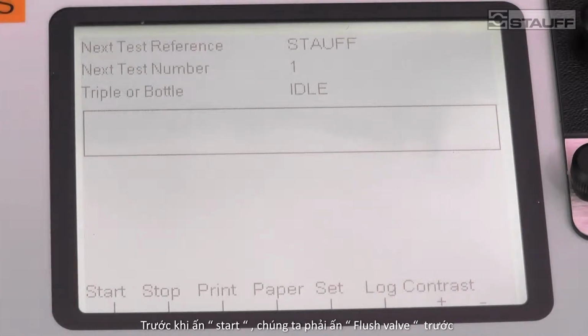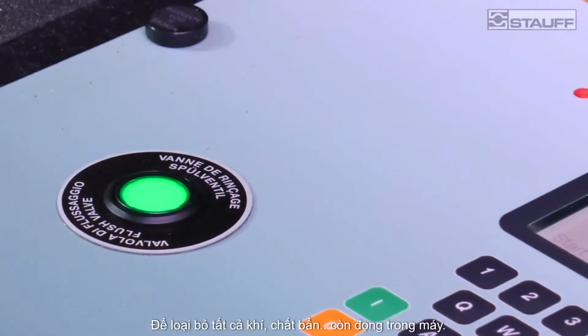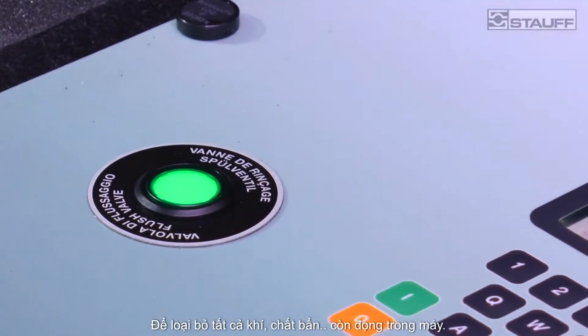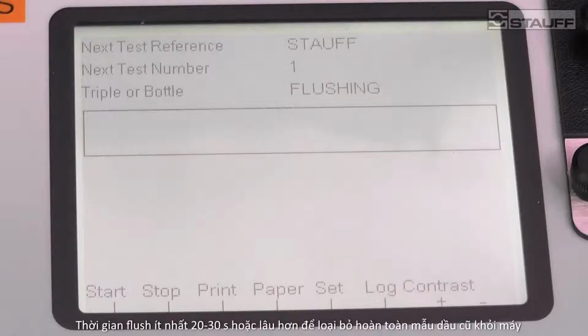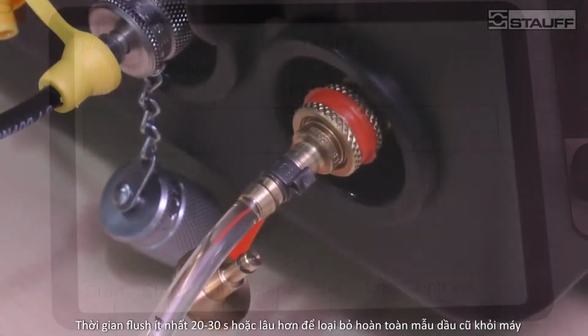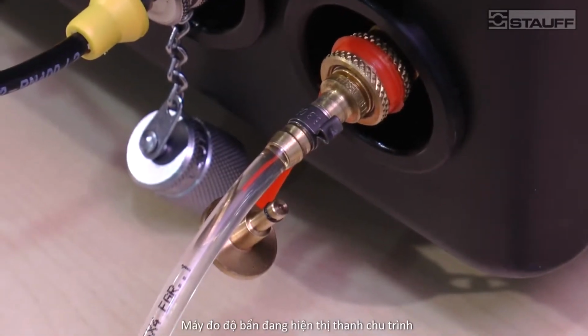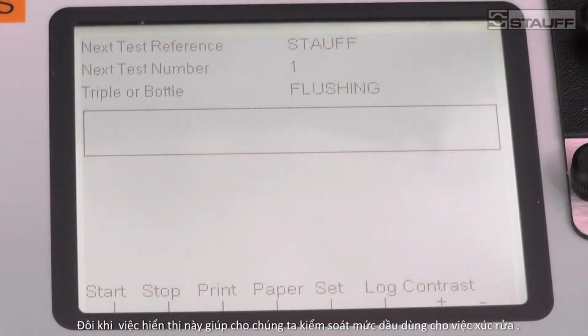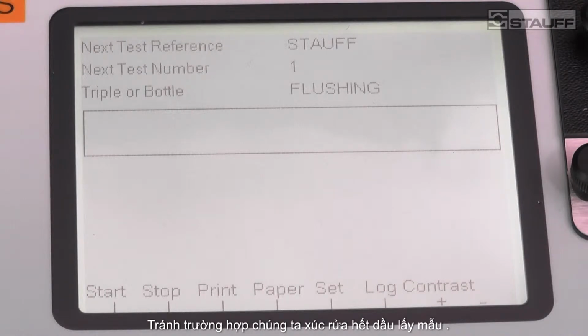Before you press start, ensure that you flush the particle counter to remove any old oil or any air that's been entrapped in the system. Make sure you flush for at least 20-30 seconds because you want to give that particle counter a very good flush and not influence it by any other oil that was left from the previous test. So the particle counter shows flushing mode. Sometimes it's a good idea to mark the bottle for the level that you want to flush, to make sure that you don't run out of the oil sample.